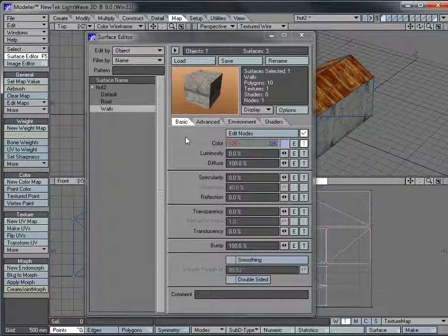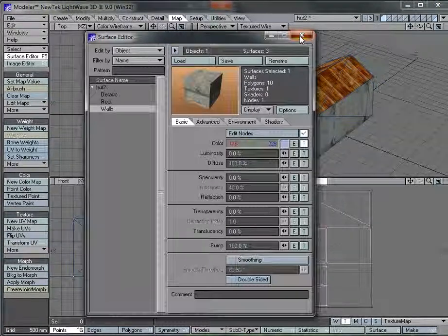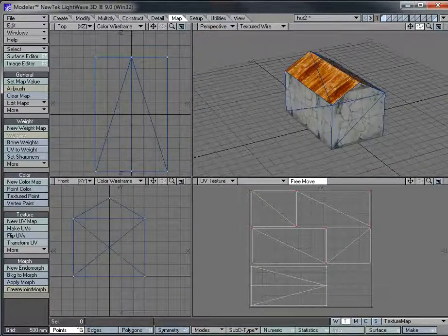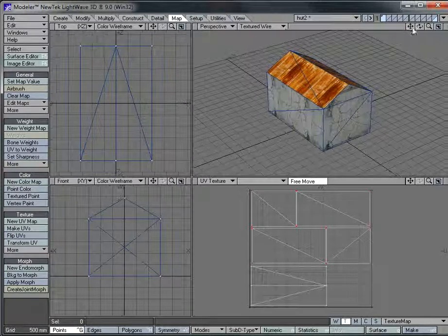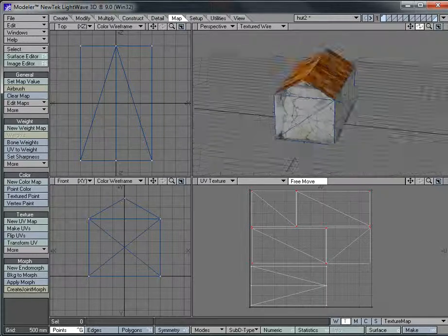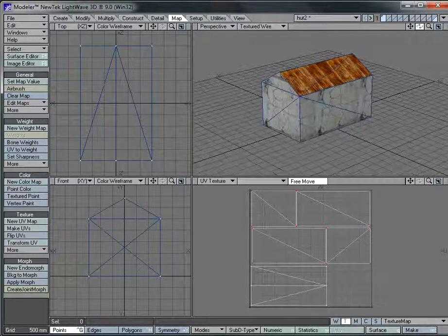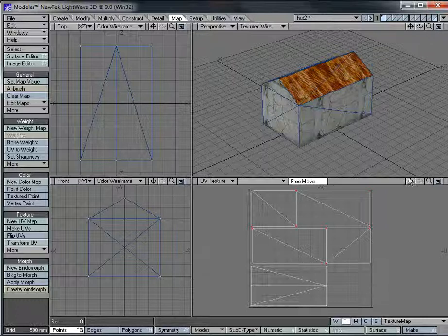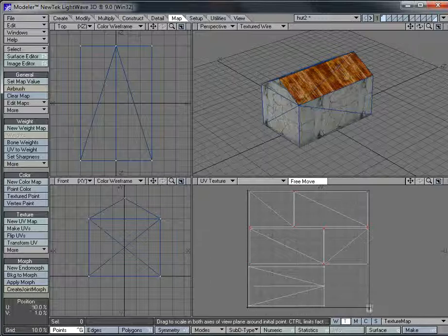Right, so this has now caused a bit of a problem, because while LightWave and other 3D graphics programs are able to render procedural textures, this is actually quite slow and the graphics card can't do it. So we can't provide a procedural texture to our DirectX graphics card. It just won't work. So what we need to do is create a texture map using a UV map, which we'll create now, and then through a process called surface baking, take the textures we have created and the procedural textures and convert them all into a flat image.